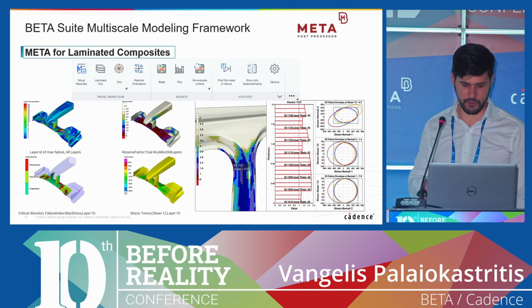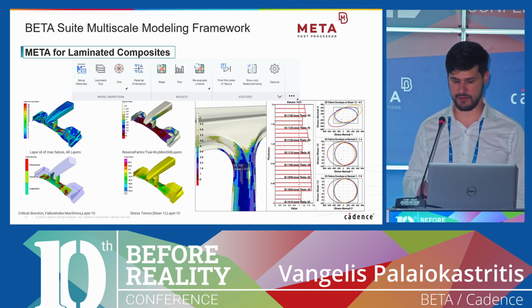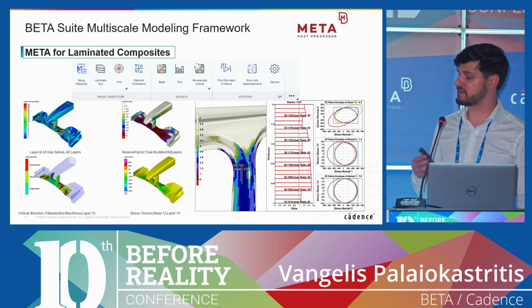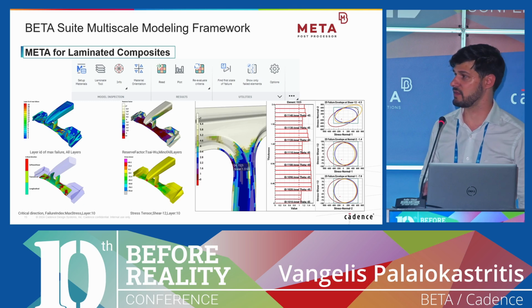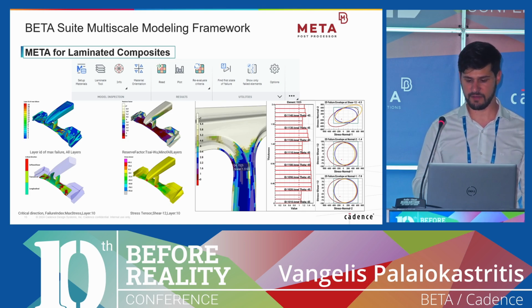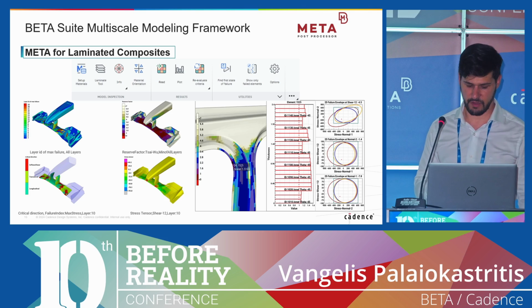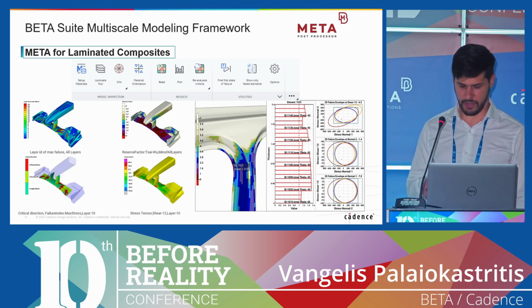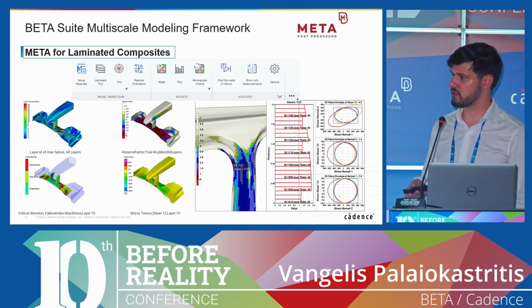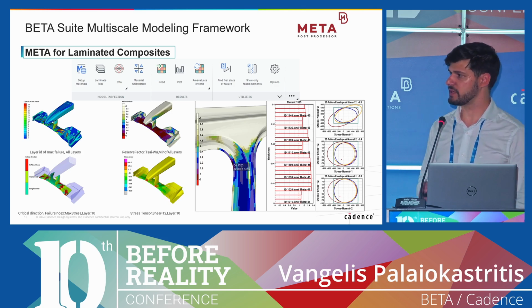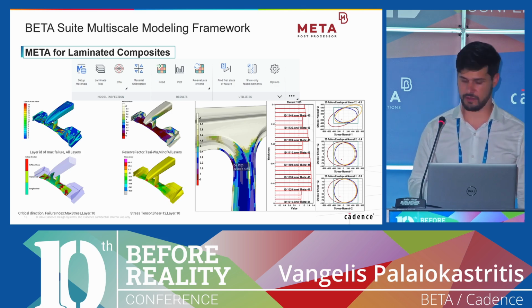Moving on to post-processing, Meta streamlines the post-processing for composites by extracting and visualizing results per layer, generating through-the-thickness plots, calculating failure indices and failure envelopes, and of course, we can take advantage of the automated reporting and all the automation capabilities of Meta.